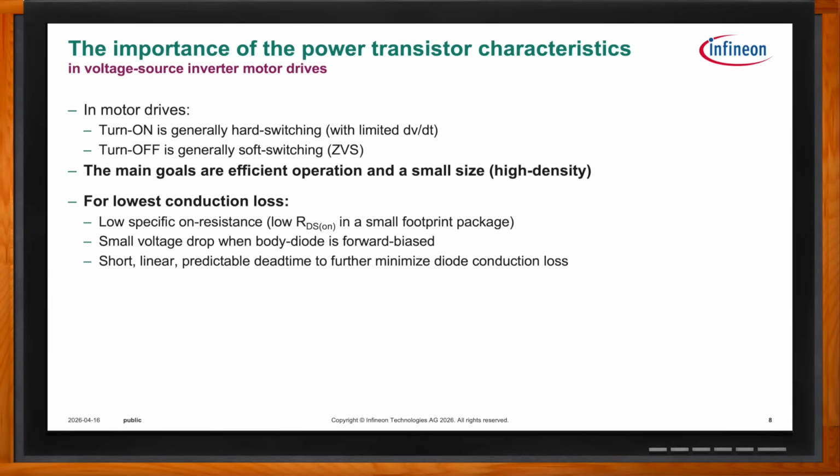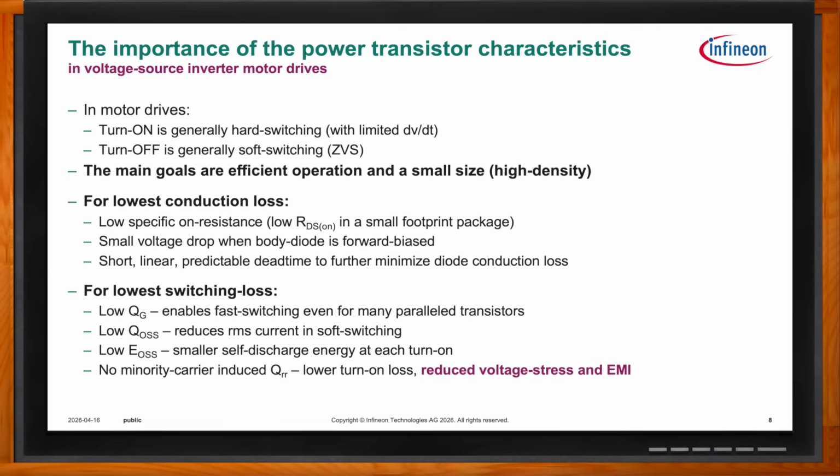Now for switching loss, what we care about is typically charge. So not only the gate charge, QG, by having a low gate charge for a given gate driver, I can get very fast switching, even if I have a bunch of parallel transistors.